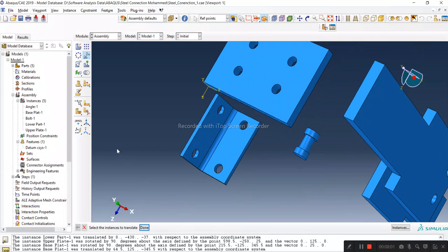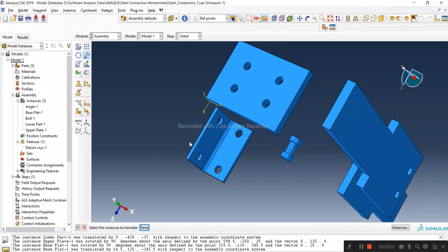It has to be 76 mm, but okay, let's do that first, because if you set up your model, meshed it, and after that you change anything, the mesh and everything will be deleted, the loading protocols that you have applied, or any instances, the interaction that you define, so everything will be deleted. So it is always better to do the meshing, the interaction, and all this stuff at a later stage. But first, just come up with the accurate dimension and accurate everything.